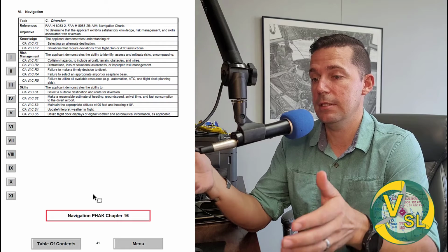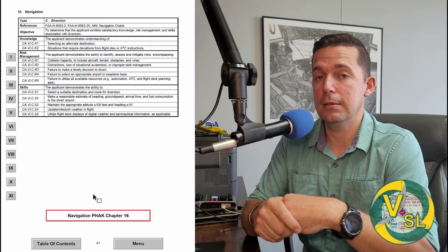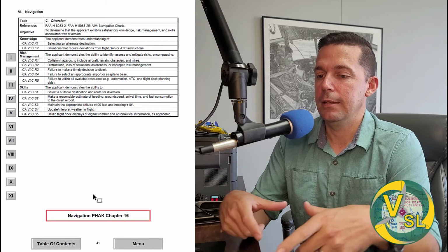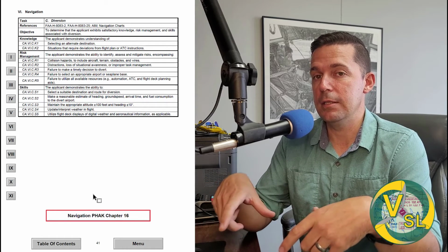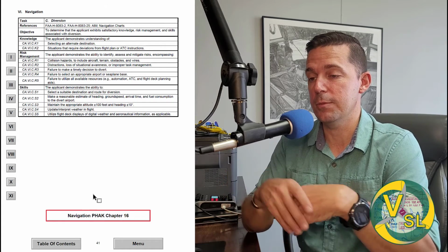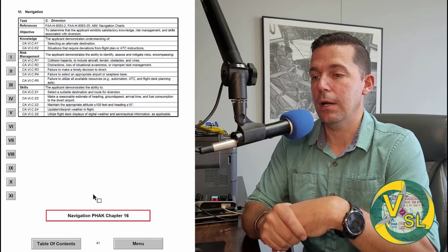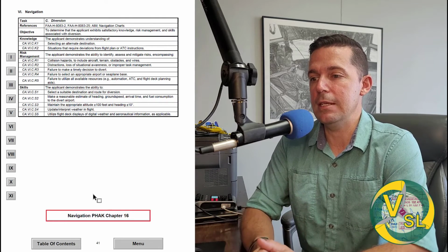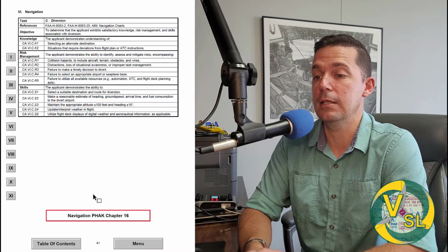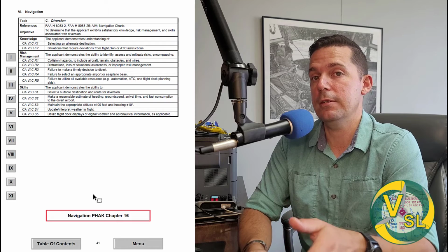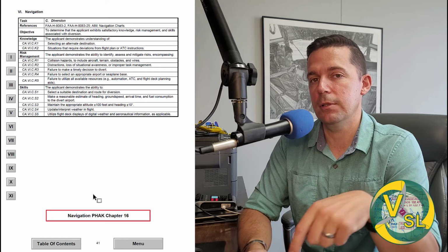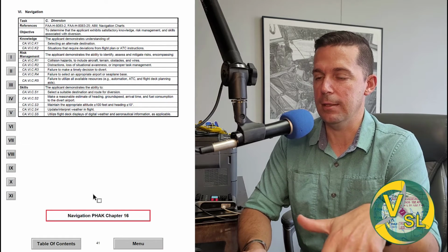Hey, that's fine, but this information is going to be calculated either by giving a really good estimate or by actually breaking out a plotter and E6B in flight, which is going to be more difficult than using ForeFlight for sure, especially in a single pilot environment. So I would recommend having some sort of EFB and also a backup, because another thing that I might present during the check ride is, oh, well, it's great that you're using your iPad and ForeFlight to estimate the diversion to this airport, but guess what?